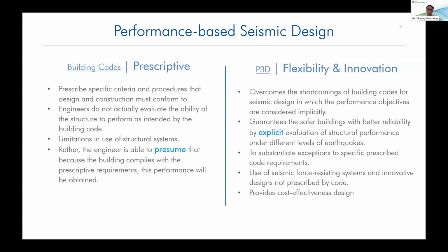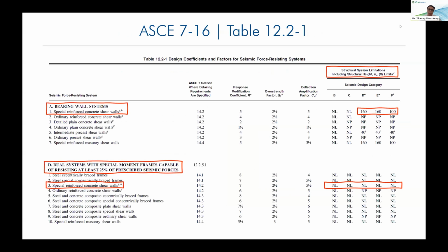One last thing is the cost effectiveness of PBD. We can reduce reinforcement where it is not required, even if the code provisions require it, because we can do so confidently, and provide additional rebar where it is required, because our analysis is more detailed.